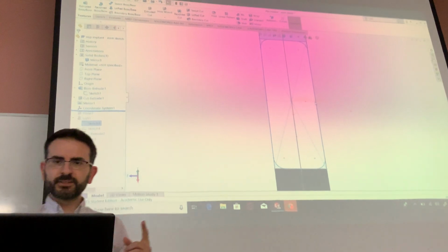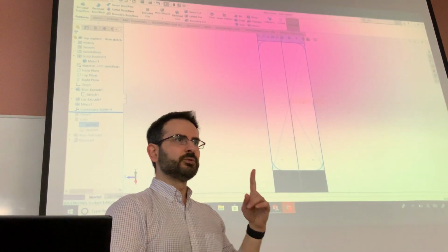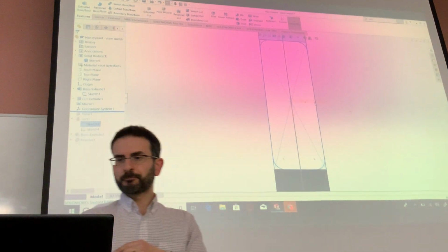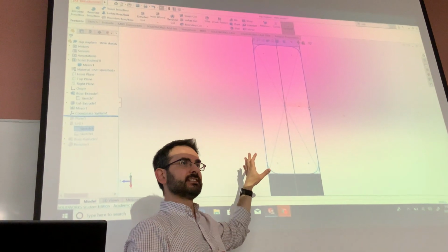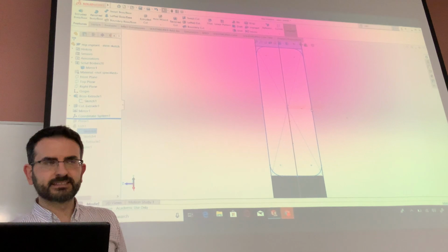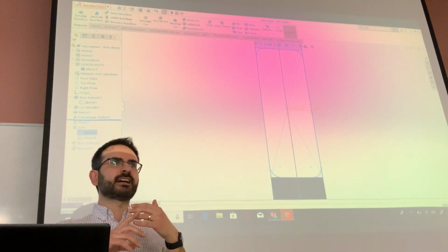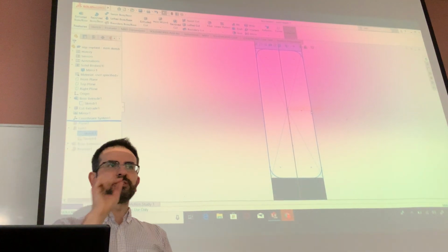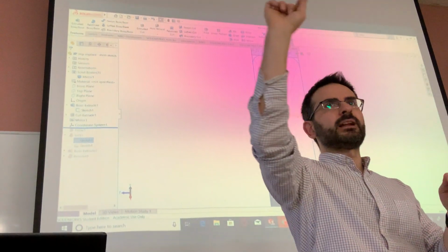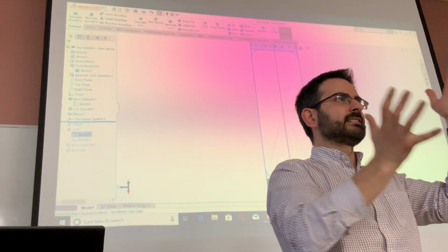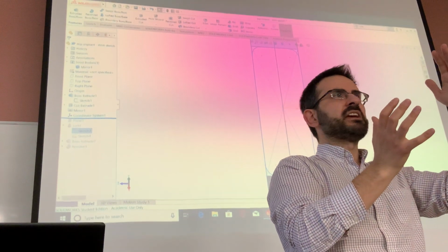Now, at that point, the one thing that I did was to create the rectangle, and because I know where I want the rectangle to be centered, I use the function that is center rectangle. And so the way to do it is that you first click on the center point, and then you pull out, and it creates this stretchable rectangle.